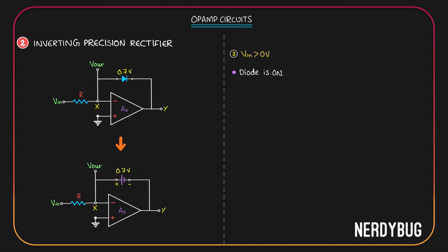There is another way to look at it. Op-amp gives negative 0.7 so that the diode is on, so that current can flow through the resistor R. How much current? Enough so that the potential across R, which will be IR, will be equal to the input, which means all of input will drop across R and potential at X will be equal to 0.